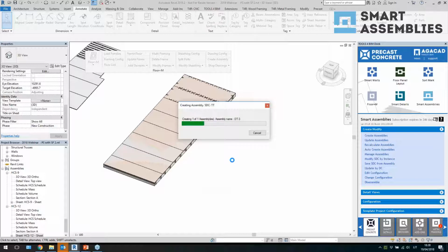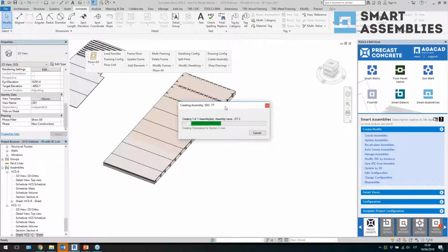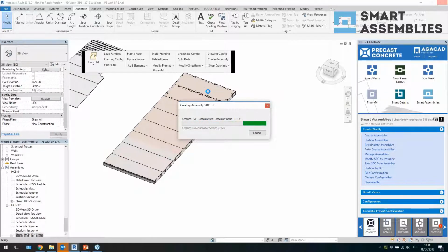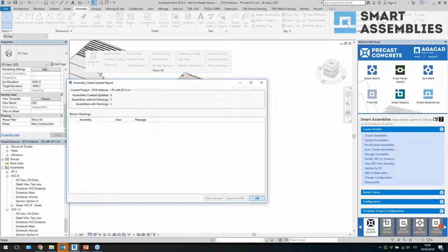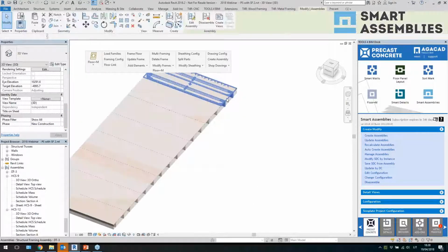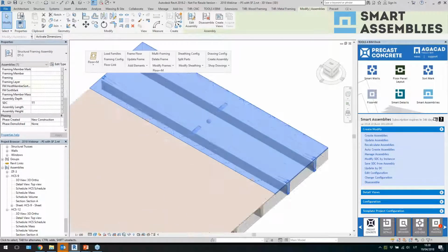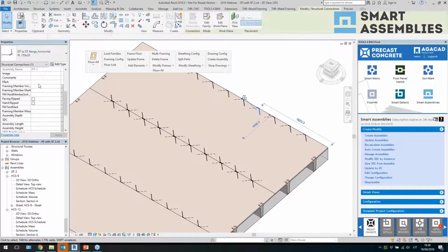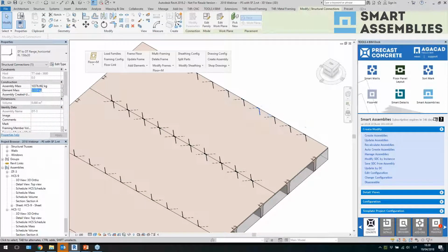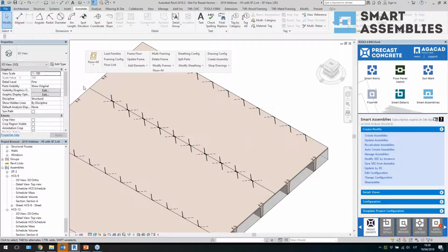So it will create the assembly for me, and also place dimensions and create a gravity point, if all of the solids in the assembly have density in the material. So the gravity point can also be created, right? And each of the details has element mass and then assembly mass, right?